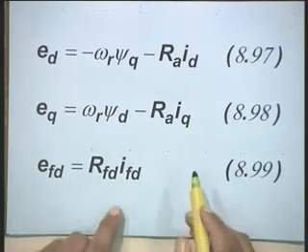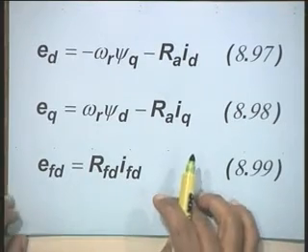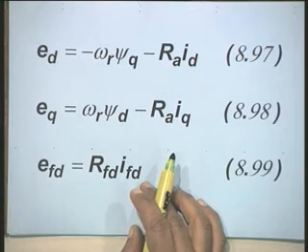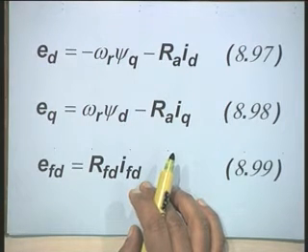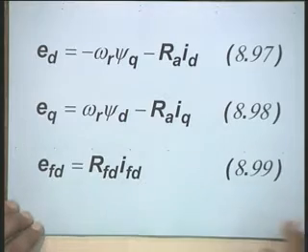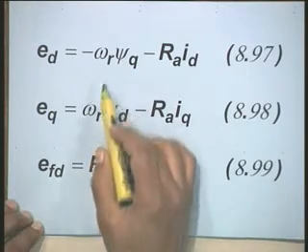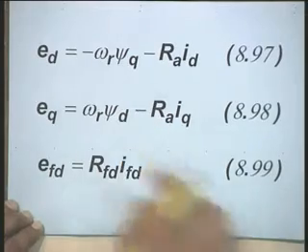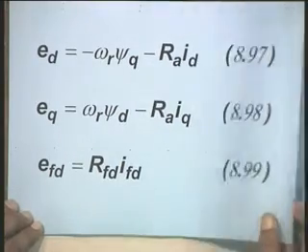It is very simple actually. In all three equations, the p psi terms, that is the derivative terms, have been set equal to 0. Now, under steady state operating condition, the rotor speed is equal to synchronous speed. Therefore, we substitute omega r equal to omega s, and in the per unit system, omega r is equal to omega s equal to 1.